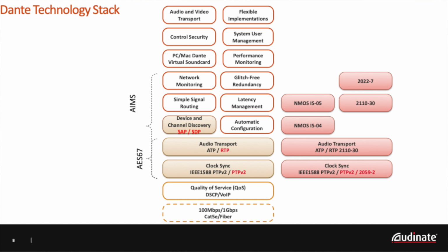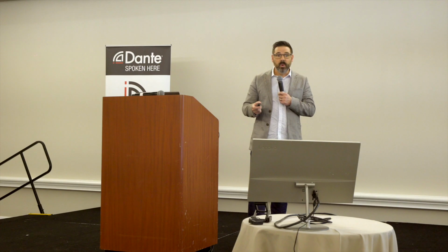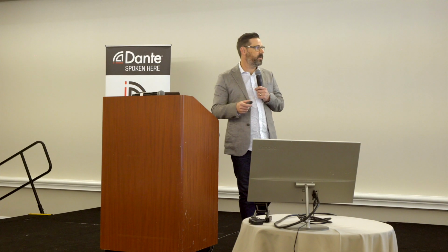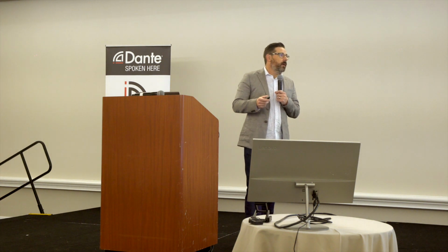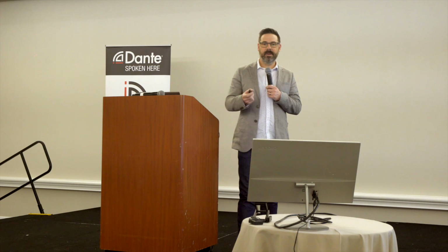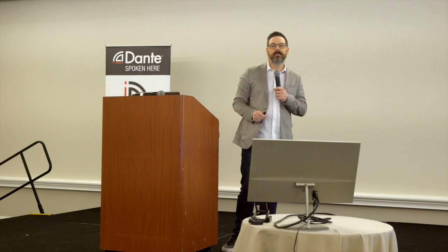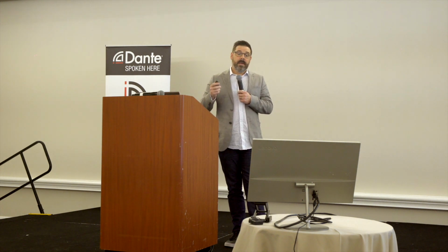We use some of the features that are in the network, you know, QoS, that was inspired by voice over IP, that's why it works. We use protocols for clock synchronization, so that's in there. Transport for the audio, we've got an RTP-based solution for doing that. But then on top of that, we keep adding features, things that actually solve problems. So label-based routing, the ability to give a device a name and then find it by that name and then say, you know, mixer, I want you to send your audio to amplifier. Really, really simple, but that actually is based on a whole bunch of technology.